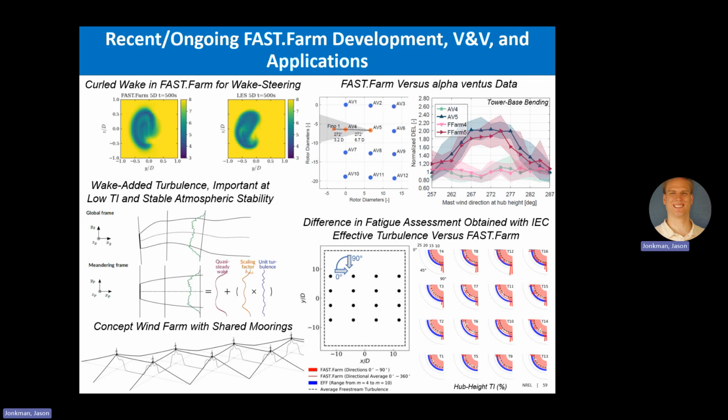So this was just taking a study where we took this 4x4 wind farm of 16 turbines, and we did a full range of wind directions and wind speeds, and we asked, how do these two models compare? The standard says you can use both. Do they get the same answer or not? I think what we showed in this work is that on average, the models actually do very much agree at the mean value, but if you run tools like FastFarm, you get much more information, like the directionality. You see it there.